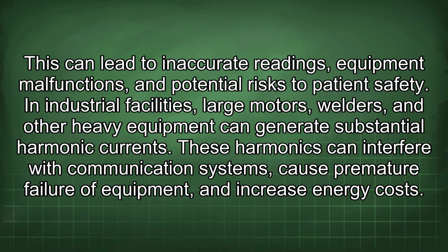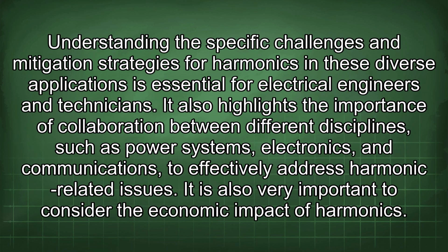In industrial facilities, large motors, welders, and other heavy equipment can generate substantial harmonic currents. These harmonics can interfere with communication systems, cause premature failure of equipment, and increase energy costs. Understanding the specific challenges and mitigation strategies for harmonics in these diverse applications is essential for electrical engineers and technicians.